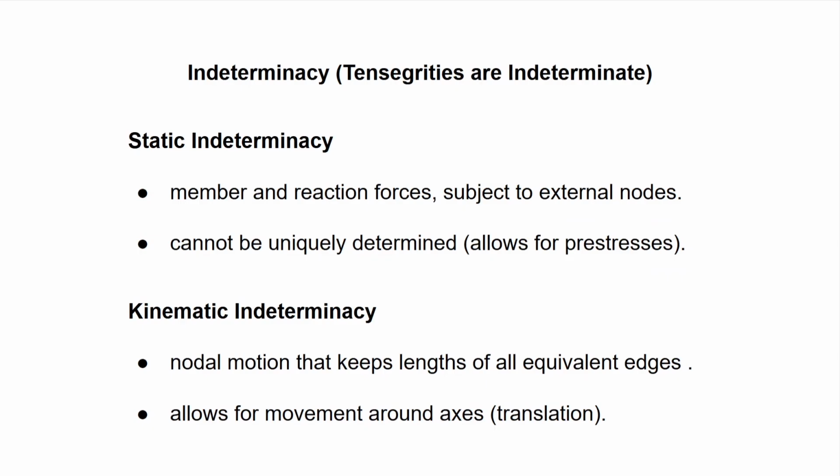The last slide I want to talk about is these indeterminacies. Tensegrities are indeterminate, and as Susan's discovered, that makes them hard to simulate in, say, a standard multiphysics software. This is just a property of tensegrities. You have static and kinematic indeterminacies. Static indeterminacies are these membrane reaction forces subject to external nodes that cannot be uniquely determined. Static indeterminacies are related to pre-stresses or allow for pre-stresses.